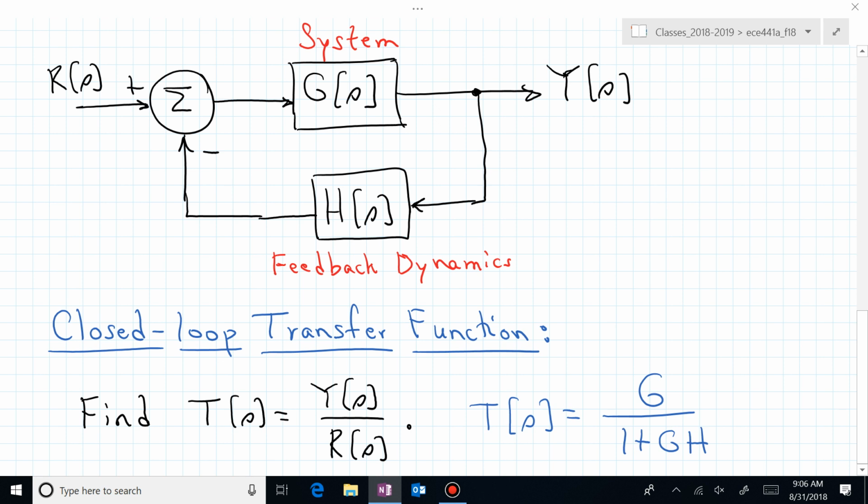That's actually, it's the fall semester, it's a Friday, it's before the game. This is our second cheer of the semester, right? We have the A, B, C, D cheer. That was cheer 1. Give me an A, give me a B. Do you remember what that gave you? The transfer function in terms of state space representation, C times the quantity sI minus A inverse B plus D. That's what you'll scream out if somebody says, give me an A, B, C, D. Here, somebody might say, give me a G, give me an H, then you give them G over 1 plus GH.